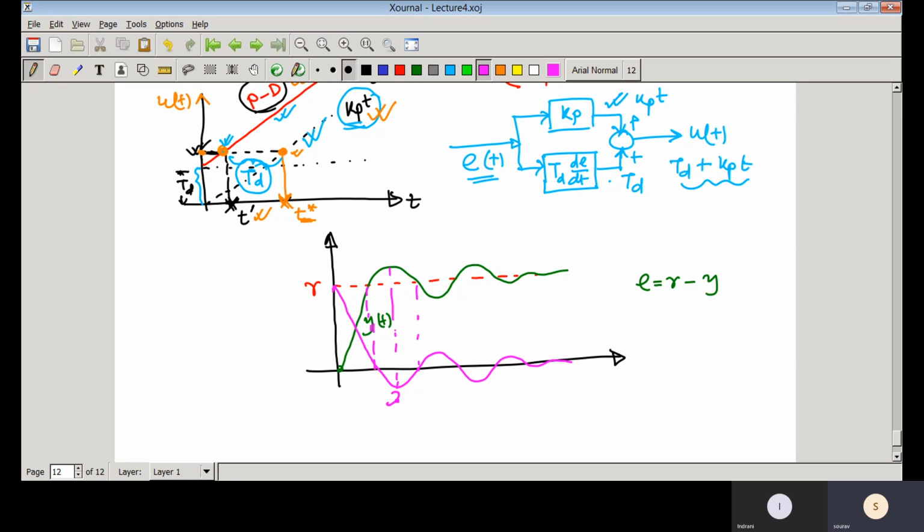So this is your error signal e(t). Now from here you can see, what is the slope? The slope is negative. Whenever the output is increasing, you see that the slope of the error is decreasing. And when the slope is decreasing, as the derivative control action is de/dt, since this slope is negative, this particular part will generate some negative input. That means the effect would be reduced.